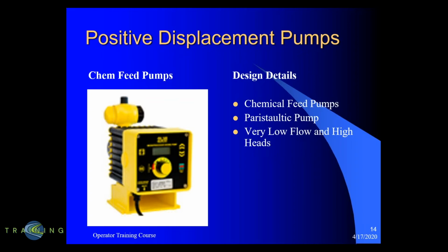It is also a positive displacement because you're squeezing the tubing as you push the chemical out of the tubing. It responds and then allows the flow to come back in. So it is a positive displacement. These are very low flow but high head opportunities with positive displacement pumps and chemical pumps.